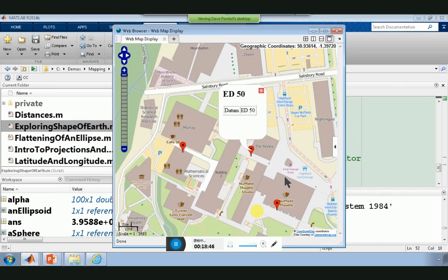As a matter of fact, the definitive way for converting between the different North American datums is based on a least squares fit between many, many survey points in the different datums. So I mention this because when I was converting a single numeric value of latitude and longitude between the different datums, for the European datum of 1950, I actually got 2 different values from 2 different calculators, and the other one happened to be in a completely different building. So that was just different implementations of the conversion routines.